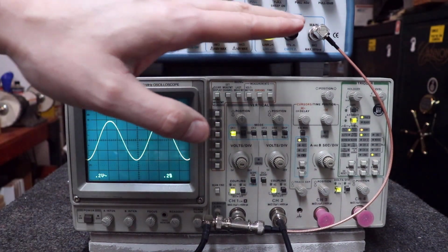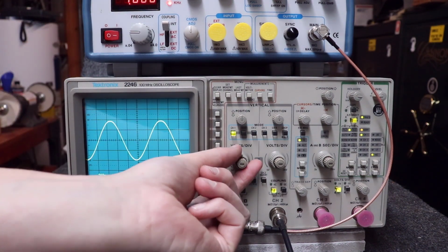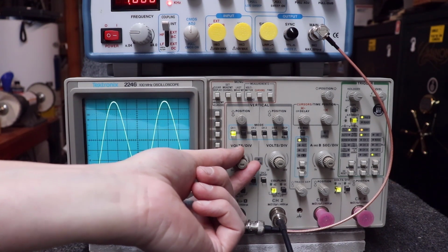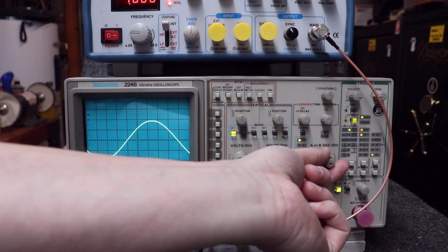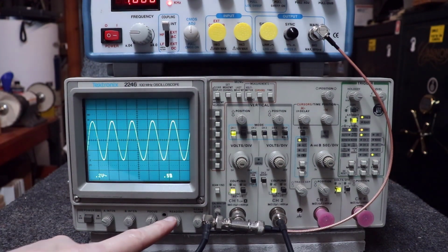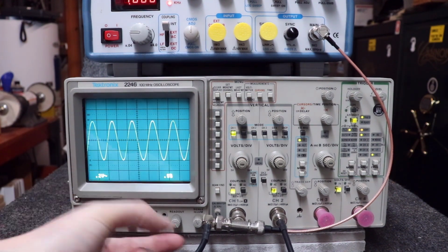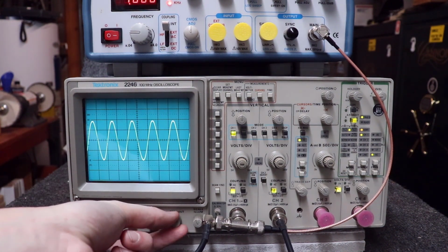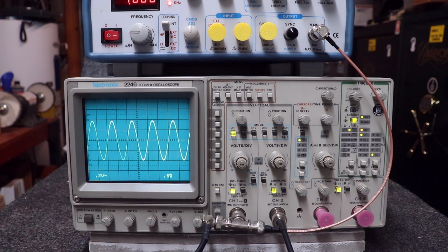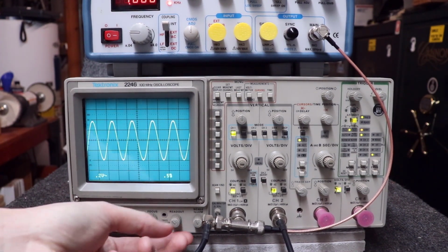I never varied the signal. I'm zooming in and zooming out on that signal via more or less volts per division and more or less time on the other axis, okay? So this readout knob is the intensity of that little readout. If you notice, I got it super bright, or I can make it completely go away there. There again, I just put it bright enough that I can read it and no more, and leave it like that, okay? And last here, you've got something called scale illumination, okay?